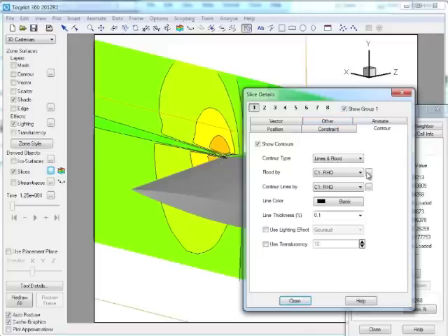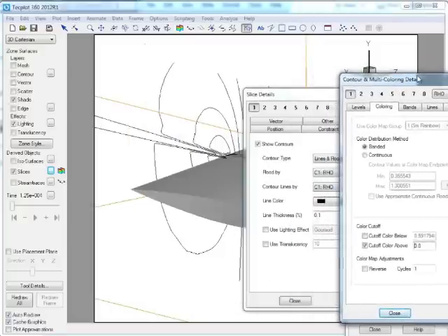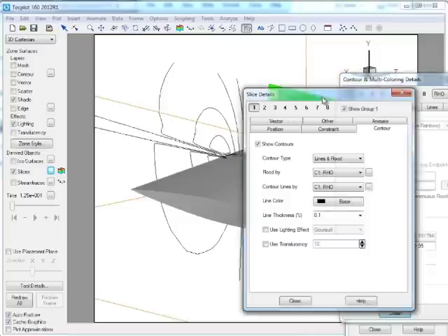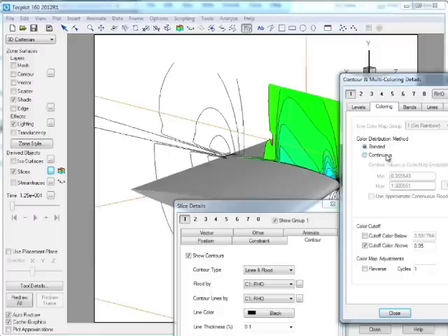And on the contour, we're going to adjust what's shown on screen using a color cutoff. And you can really say, I'm going to cut it off above a particular value. Now, in this case, I think you can choose something like 0.8. But if you use 0.8 and you're not seeing enough of the contour, you can change that to 0.95. And you can really spend the time trying to figure out how to get it to the right set of values, and it looks like that's more or less okay, because it's identifying the area of interest.